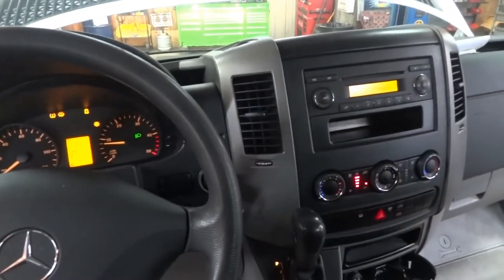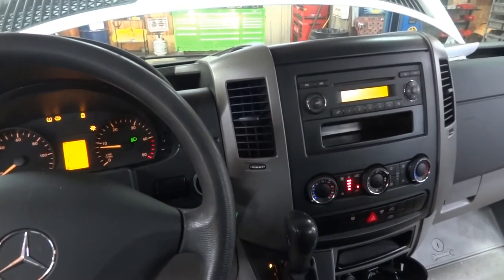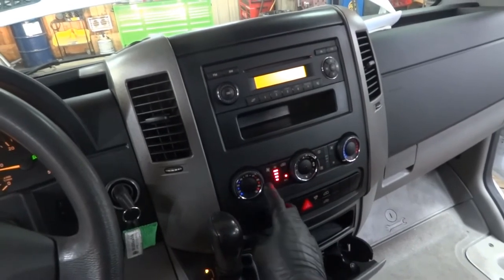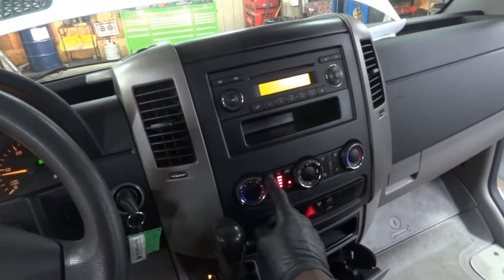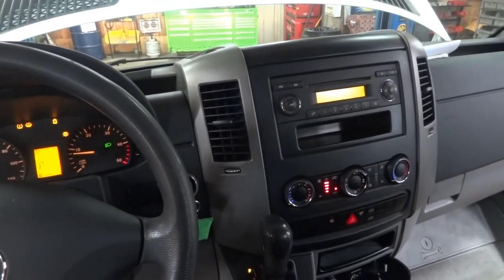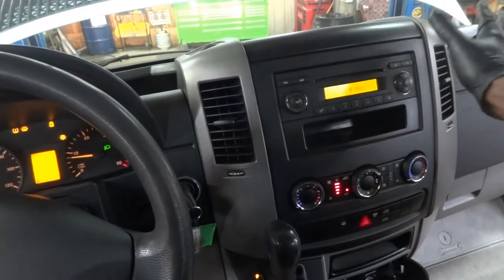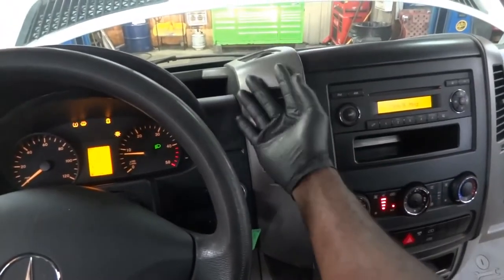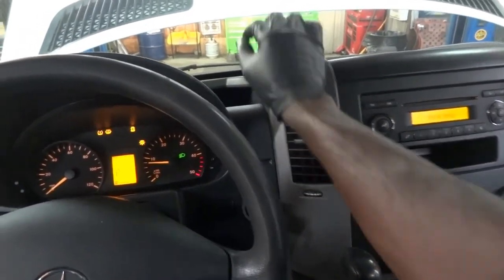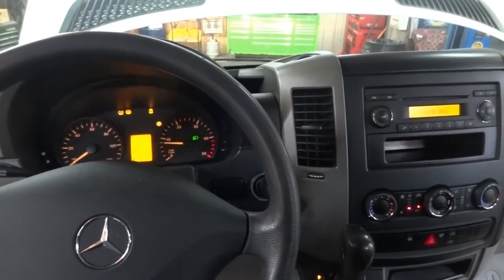So we are either dealing with a defective blower motor or a defective blower motor regulator, or maybe a wiring issue, or it could just be a fuse, who knows. So right here, customer's complaint confirmed. This is gonna steer me towards a blower motor or a blower motor circuit. We have to see why this blower motor is not blowing any air, and I believe the air conditioning is just fine. If the blower motor was working, you guys could hear it. It's not blowing any air. I'm not feeling anything. So I'm gonna turn off the van so we can talk about our plan of attack.